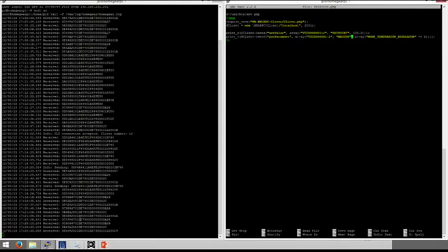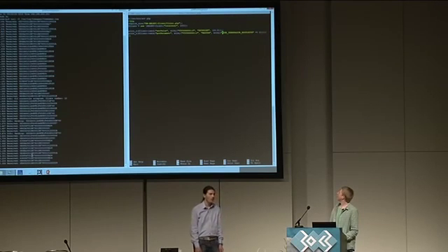And the second RPC function we are using is put_param_set. Put_param_set is used to set configuration parameters. So we are using put_param_set to change the mode of the thermal control to central mode in case it is not in central mode. And again, this information is out of the XML file. We change the variable mode temperature regulator to the value 2, and 2 is the central mode.